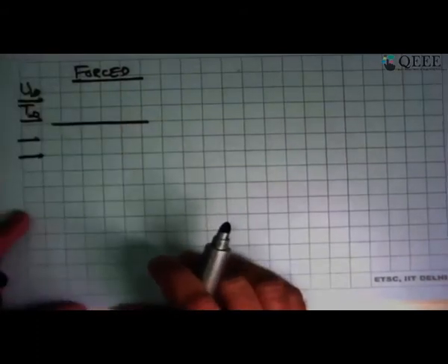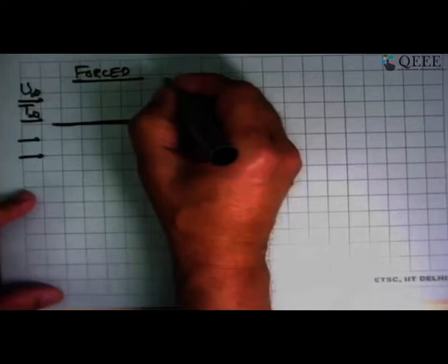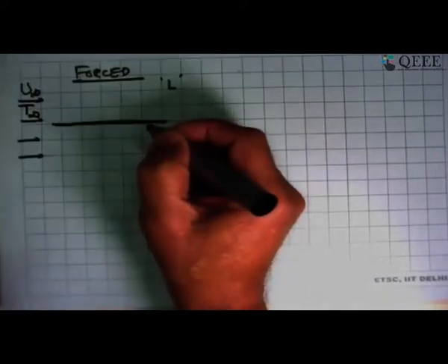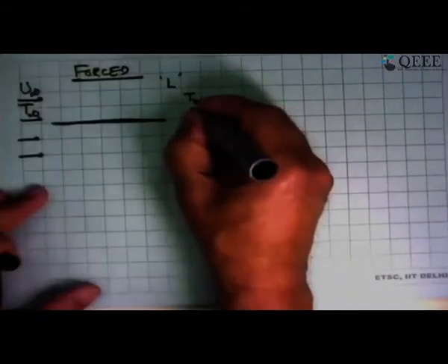we take flow past a plate aligned with the flow. So this is a uniform, steady flow, velocity u infinity. And in the companion heat transfer problem, we now also have to say what its temperature is. This is T infinity. And we have a plate whose length is, say, L, and it is either heated or cooled. And we have two ideal conditions in that. Either we say that its temperature is constant everywhere, Tw, or the heat transfer rate per unit area is constant, which is q dot double prime.